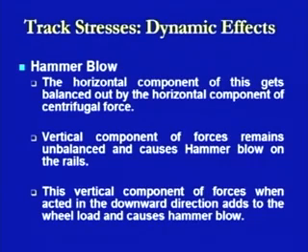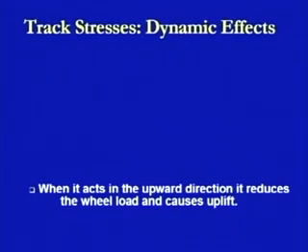In that sense, there are certain vertical and horizontal components which get induced because of the balancing out of all those weights. The horizontal component will get balanced out by the horizontal component of the centrifugal force, but the vertical component remains unbalanced, and because of its movement in the downward direction it causes the hammer blow. In case it is moving in the upward direction, then it will be relieving the stresses on that point.